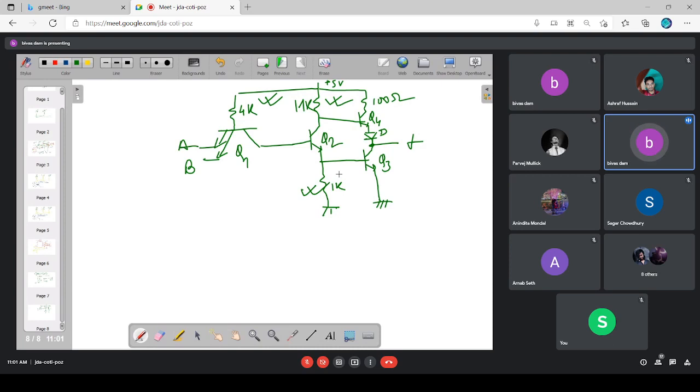That current will flow only when the corresponding device is on. Is it not? Yes, sir. So if I increase these individual resistances, the net current flowing through the device when it is on will be reduced. Now, if the current through the device gets reduced, what will happen? The power dissipation across the device will be reduced.